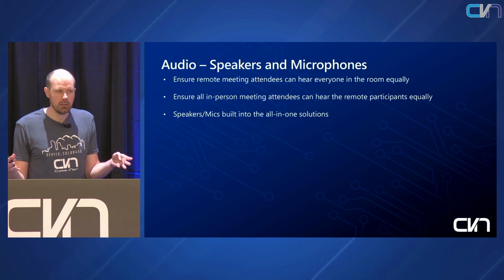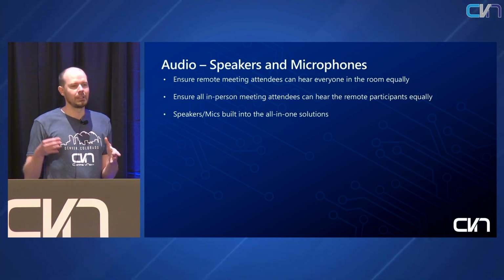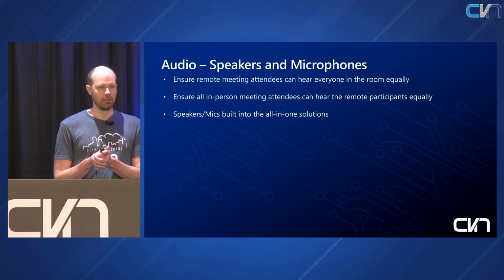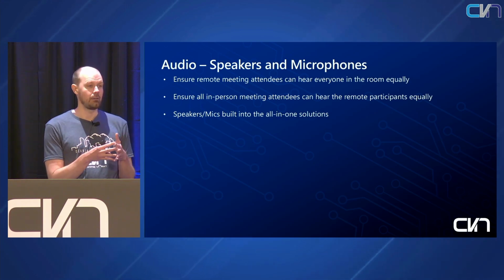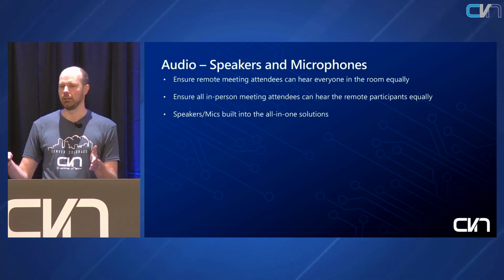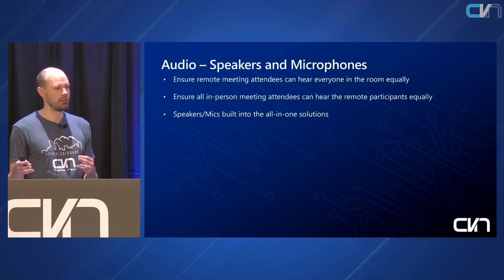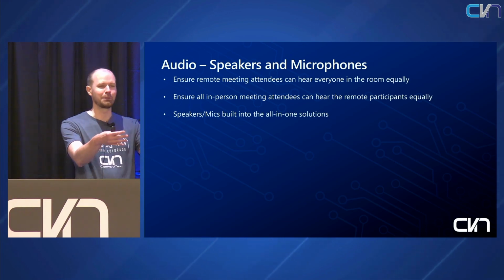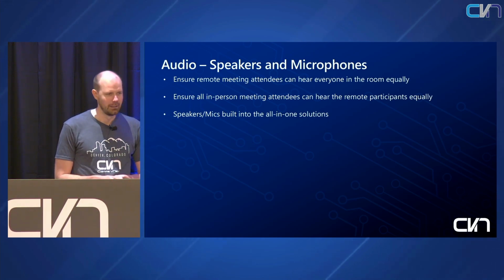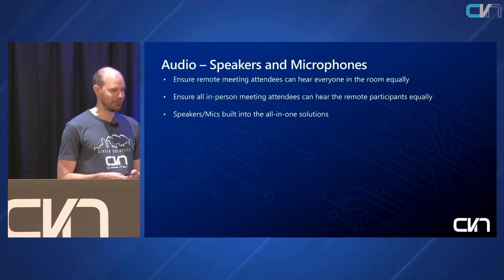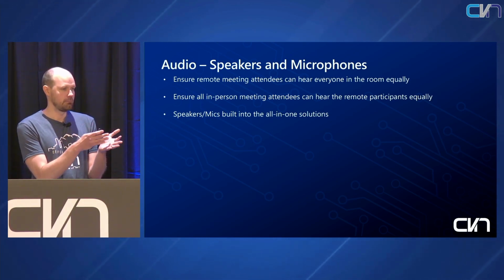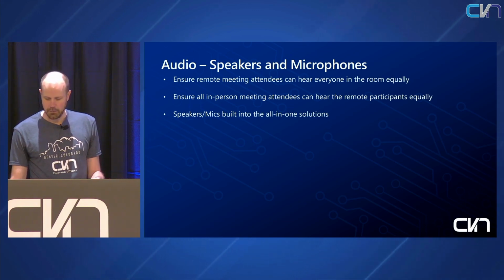That's what we have. Be careful with this when it comes to distance. If the manufacturer says this mic will reach 20 feet, make sure that that participant is not going over 20 feet. In fact, go a little less if you can. Make sure they're at 18 feet away. There's nothing worse than putting that room solution in, and someone says, I can't hear the person sitting that far away. It's a design failure at that point, right? So what can we do to help that? All right, obviously distance is key. Make sure you think about that.